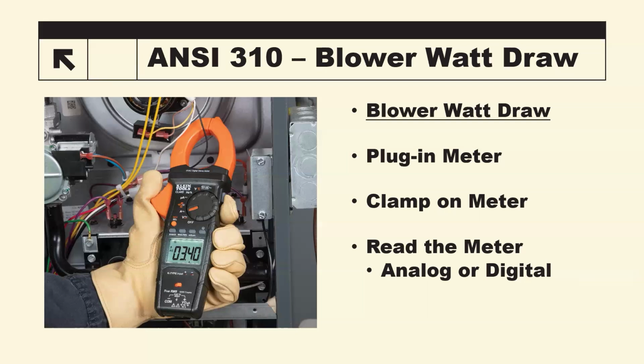Well, this goes to the fundamental workflow of the standard. When it was being developed, a lot of people were saying you're going to be adding these additional tasks, right? A rater would, at a minimum, already be doing the total duct leakage. So in the field, they're adding in the fan airflow, the fan watt draw, and checking the refrigerant.